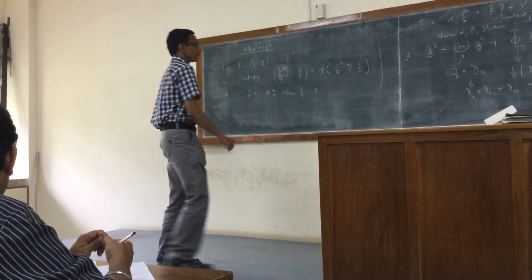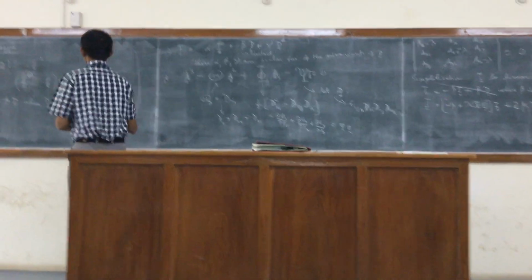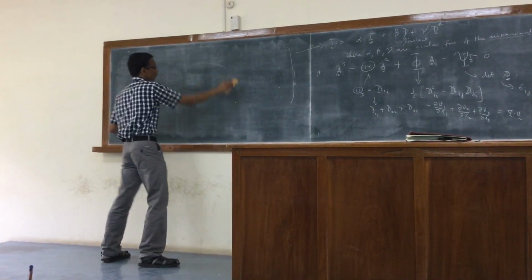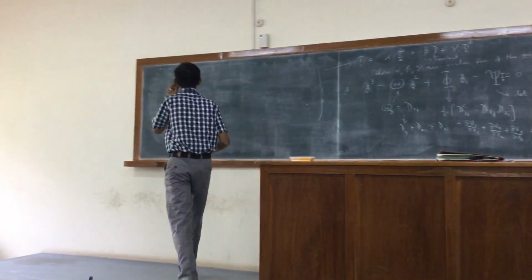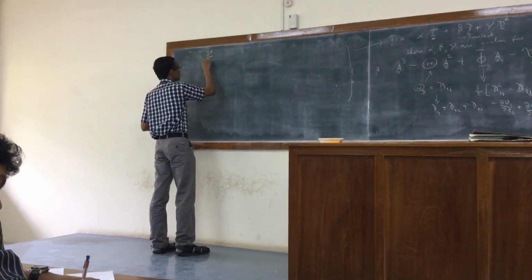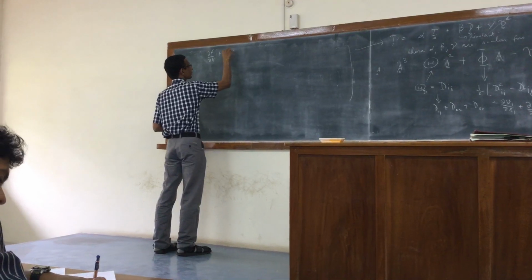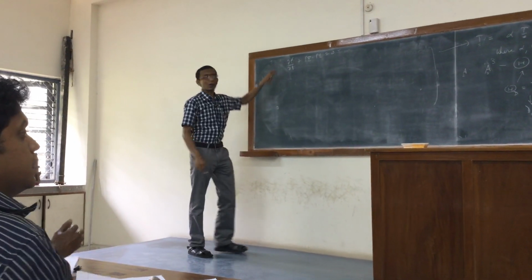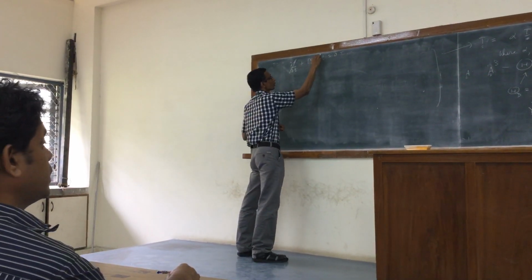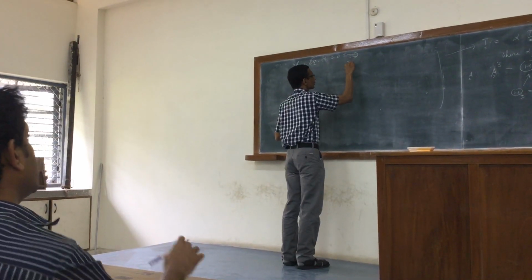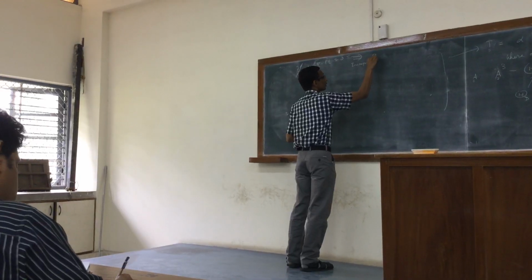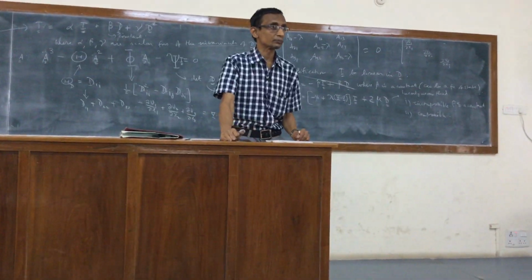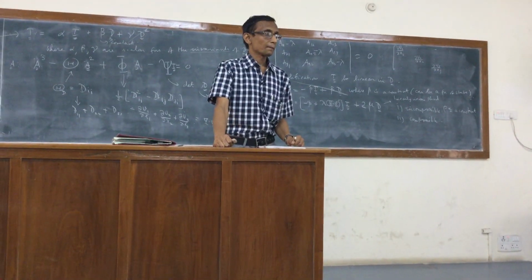Now if you look at the equation of continuity of the incompressible fluid, the equation of continuity in general we have defined without any reference to any particular type of fluid is this, right? If the rho is constant, then this is 0. This rho can be taken outside, so that means for an incompressible fluid, this will be the continuity equation, right?